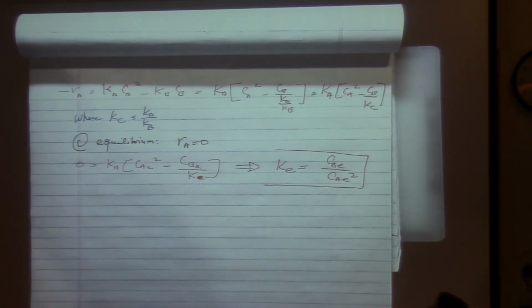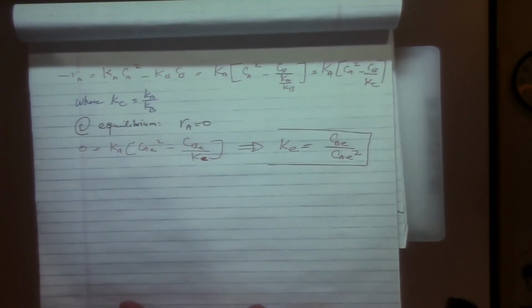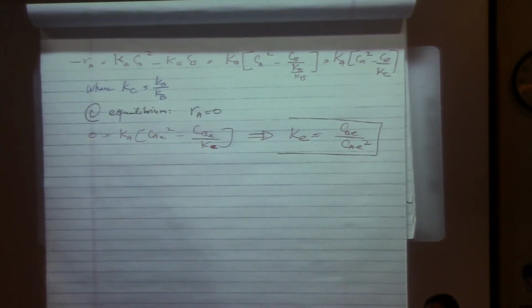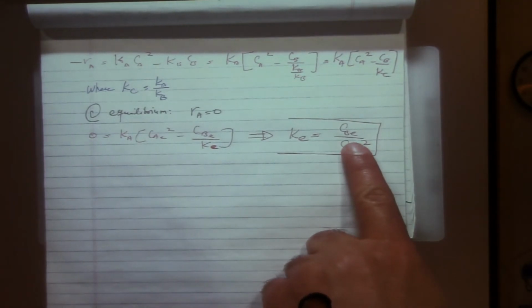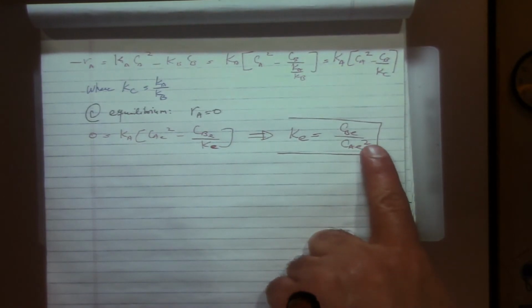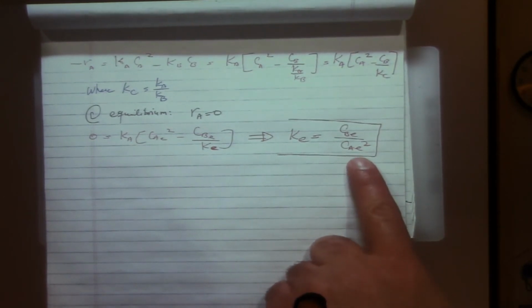Okay, so what should I do in order to calculate the equilibrium conversion now? What would be the next step? The next step would be to form the stoichiometric table, and it's a batch reactor. We know the reactions. We write down the stoichiometry, and then we use these equations. How much would be B at equilibrium at the final? We don't have this value yet.